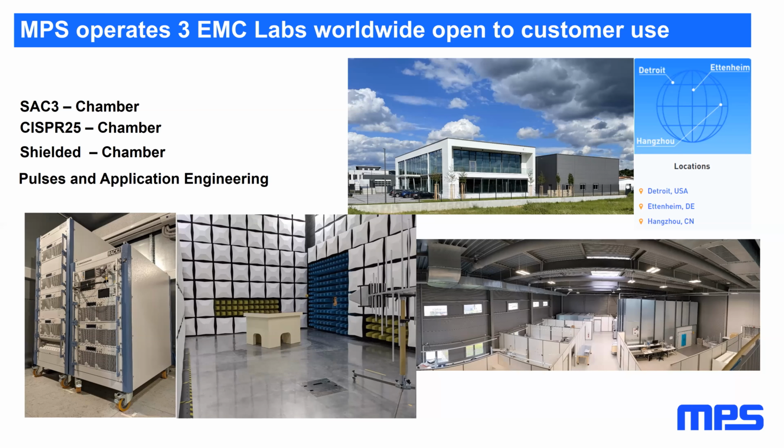Great, thank you. Next up, can spread spectrum become synchronized, which is unintended and unwanted in a system? You can, if you start with a master spread spectrum oscillator, synchronize a lot of other stuff to it. So if the other systems can cope with that modulation scheme and can be moved around, no problem. Why not? It's normally always done if you do spread spectrum on a processor clock.